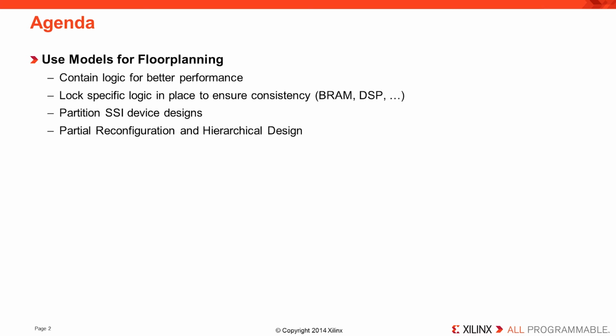And finally, another use model for floor planning is for partial reconfiguration and hierarchical design. These solutions often require floor planning to isolate the reconfigurable logic from the rest of the design. Various parameters are put on the floor plan region to ensure that no logic or routing from the outside encroaches in that space. This is covered in detail in the partial reconfiguration quick take tutorials and will not be covered in this one. So one of the big questions designers face is whether to use floor planning and how.